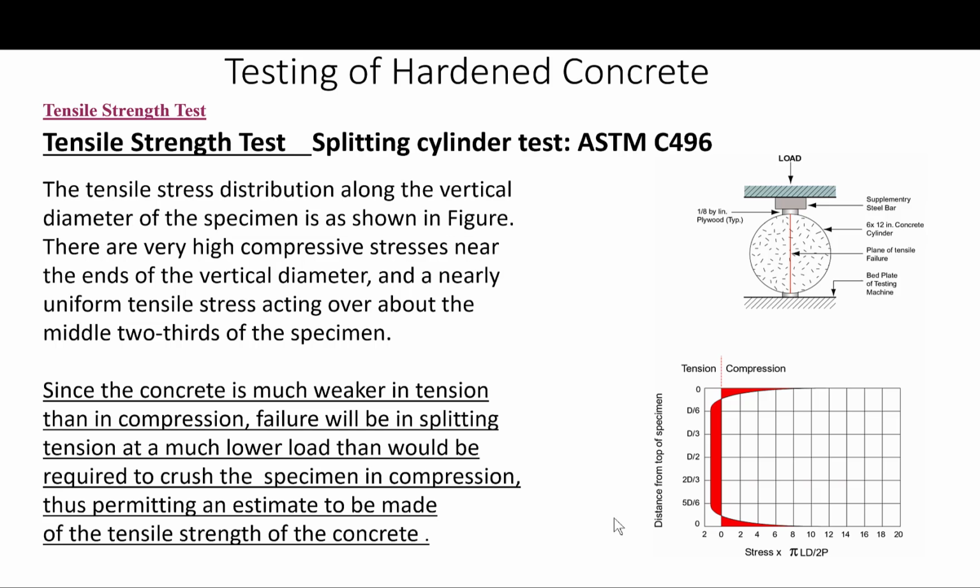In addition, some recent studies have shown very little difference between the two values of tensile strength. And, for some concretes, the direct tensile strengths have been found to be slightly higher than the split-cylinder strength. It would appear that the ratio of the direct tensile strength to the split tensile strength depends upon the strength level of the concrete and upon the maximum aggregate size.